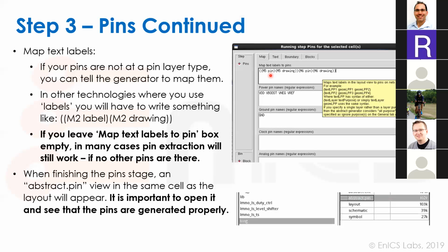No, I'm not speaking about doing the flat deliberately. I'm speaking about the option that somebody does something small and does it from scratch, and that's it. Yeah. So I think the methodology is unquestionably that you want to manually draw each and every one of your pins, how it should be extracted in the LEF. These should be on the pin layer and on the top hierarchy in your Virtuoso layout design, and then only extract those. I think one of the reasons for this mapping is that different PDKs will use different layer names and purposes and so forth, and so this allows you to kind of translate between them.